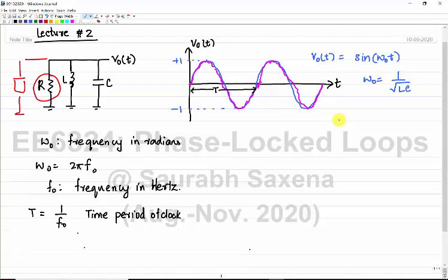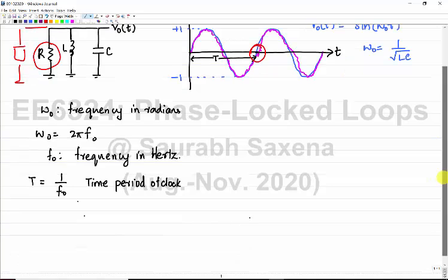But when you are going to do that, you will have variation in the output clock waveform, and that variation in the output clock waveform is going to change not only the amplitude maybe, but also the zero crossing of the clock. And if you remember, we were looking at zero crossings of the clock when we were trying to fix the data rate at fixed megabits or gigabits per second.